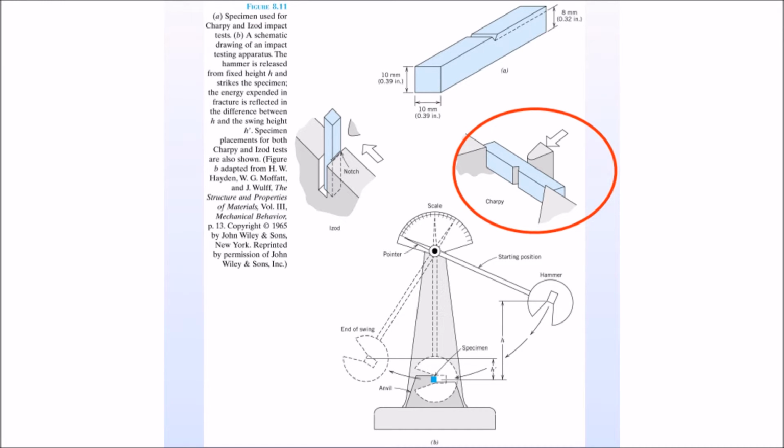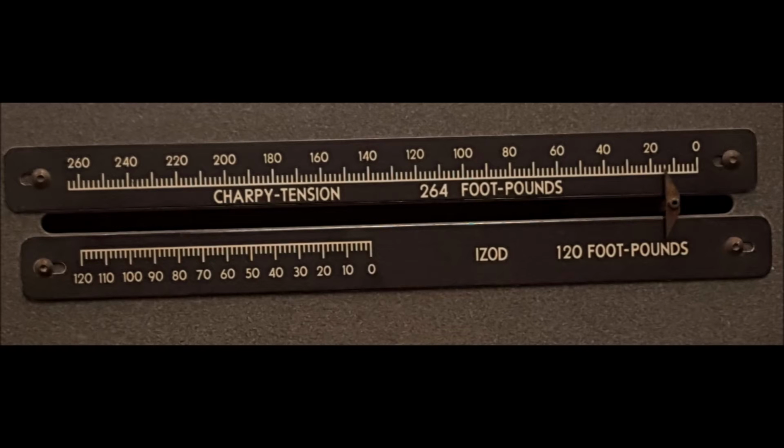The Charpy machine is able to measure the energy that it took to break the sample due to conservation of energy. The hammer's energy after it breaks the material equals its initial energy minus the energy that it took to break the sample. Because the hammer behaves like a pendulum, its amplitude is proportional to its energy, so we can figure out the initial and final energy of the hammer, and from there, the material's impact energy. Luckily, the Charpy machine reports this energy by having the hammer swing move a needle on a gauge, so the machine's operator does not have to do these calculations.